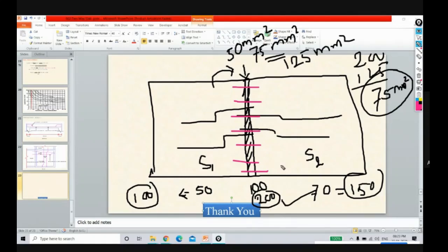And sir, for sunken slabs, what is the ideal depth, the minimum depth we need to consider for residential projects? See, the ideal depth and minimum depth may not be given in the IS code also. That depends on your material, which type of material you are using for the particular slab, for the toilet or bath. On that your depth is decided.